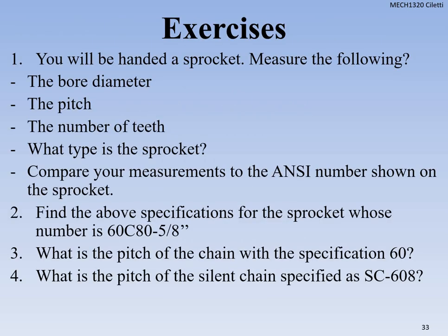Should be good. And then in class, it might be on your test, might just be at random, but I'm going to hand you a sprocket, and you should be able to give me all these different measurements for that sprocket. The bore diameter, the pitch, the number of teeth, the type of sprocket. Okay, and I might have you look up some different specifications for it. Alright, so make sure that you know how to use a dial caliper in this case. If not, I will make sure that I show you before we get to this part of the lab.